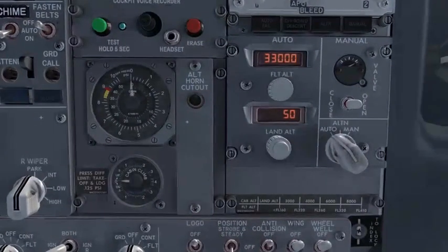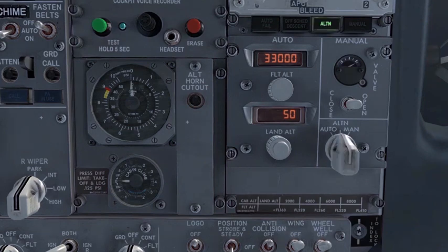Cabin pressurization also has a relief system that is provided as a protection mechanism if the pressurization control system were to fail. The cabin may be saved from cabin overpressure and cabin negative pressures. Aircraft pressurization may be controlled either automatically or manually. The automatic mode control has 2 submodes, automatic and alternate, for built-in redundancy in case one automatic mode fails.